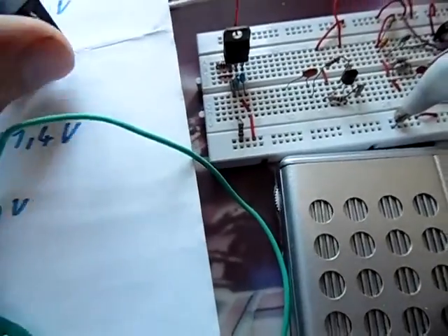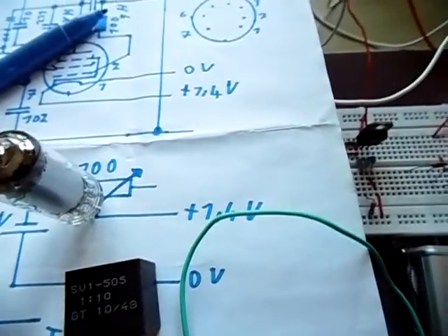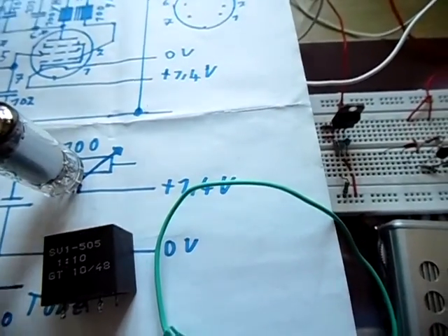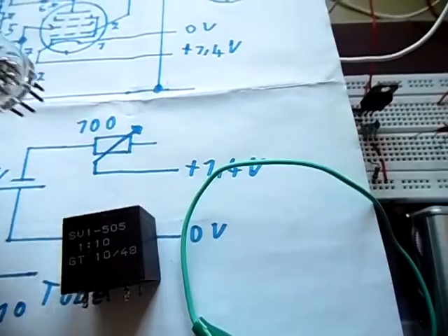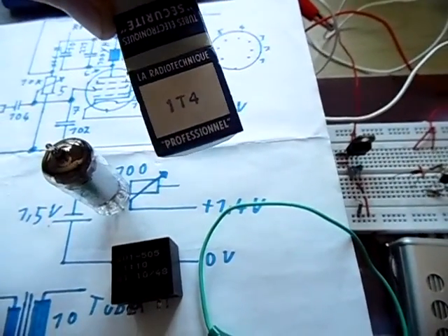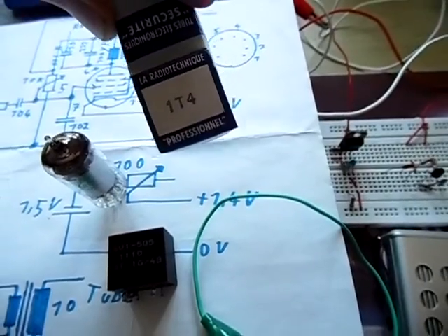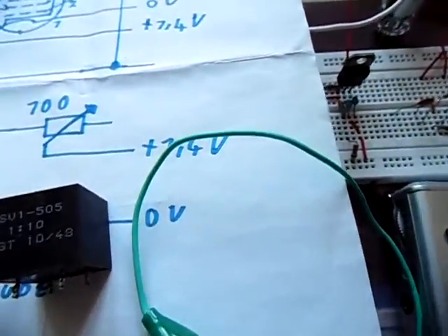If you don't have this transformer, you can get this tube and you want to make your own tube transmitter on medium wave, and it should be low voltage because you are afraid of being shocked. So you just want to get one of these battery tubes, which I said before is a 1T4, or if you just look it up, you will find many comparable tubes. Well, you can go ahead, like I did, and support it with some electronic circuits. You can make a hybrid transmitter.